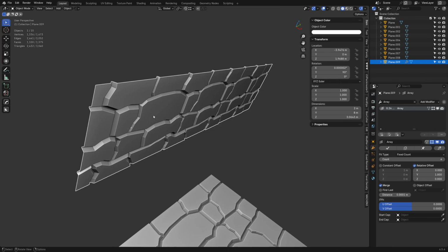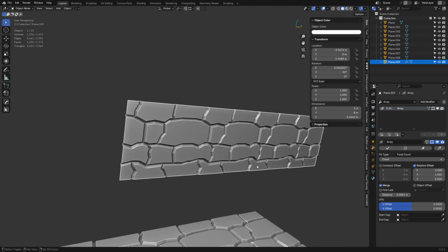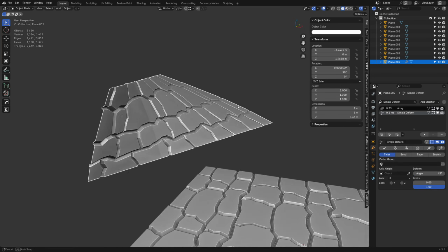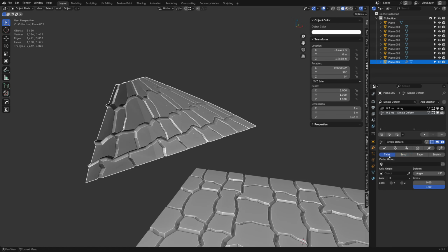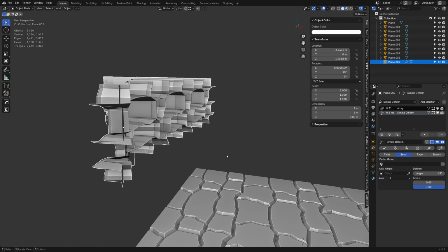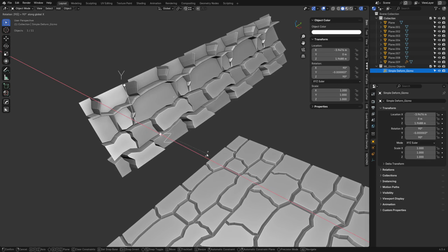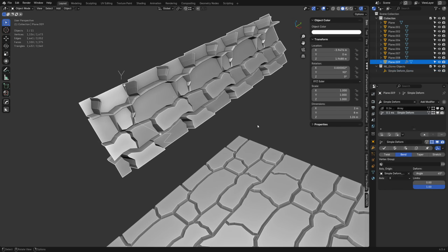Okay. And I'm going to do a bend here using the regular modifier in 4.5, but they updated this for 5 series. So bend is going to be a little bit different, but it's the simple deform modifier. Simple deform is kind of a pain to set up sometimes. We want to do, instead of twist, a bend, and it still does wrong. You have to create an empty with the modifier list add-on. It wasn't that hard. You would just create empty by hitting that button. Creates the empty. And normally I rotate these on X 90, and that usually will give me what I want.